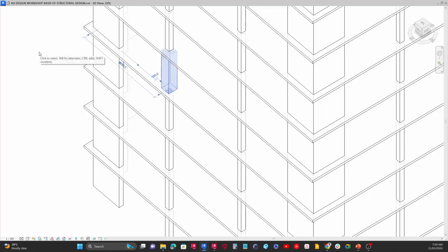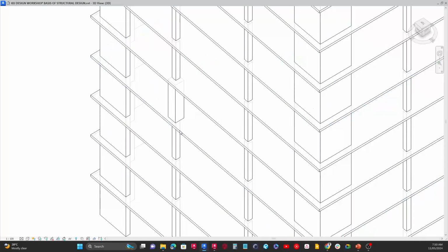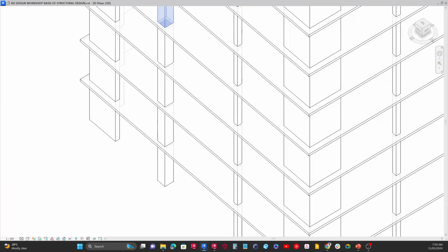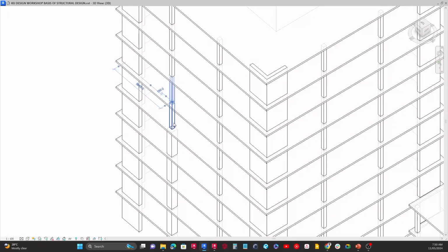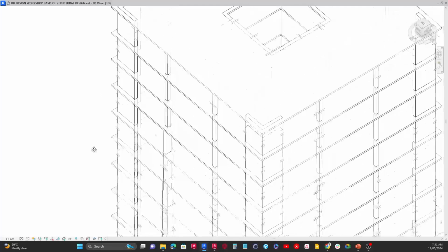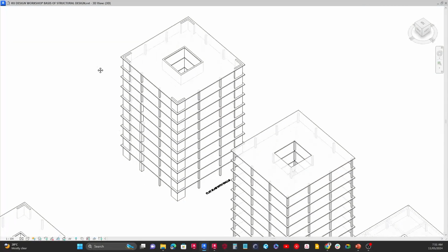So that's why you notice in building structures, as you are going down, the column section may end up increasing, something like this, all the way to the bottom. And it may not be just once, it can actually happen twice. So for instance, you can have something like this until you take it all the way down successfully.